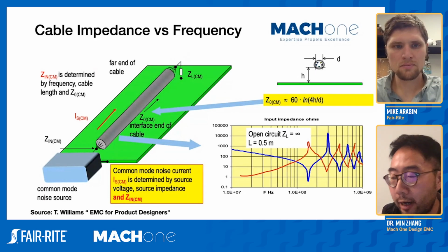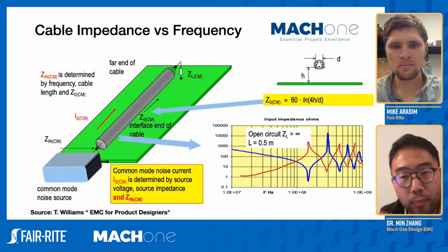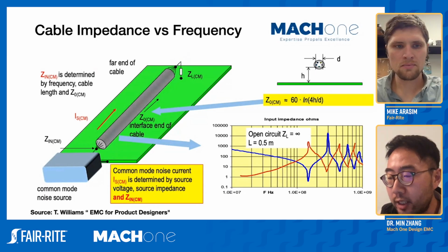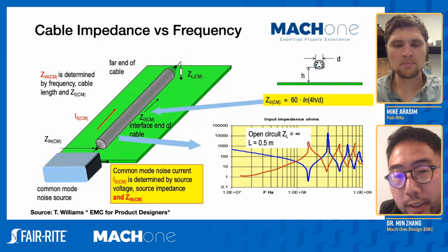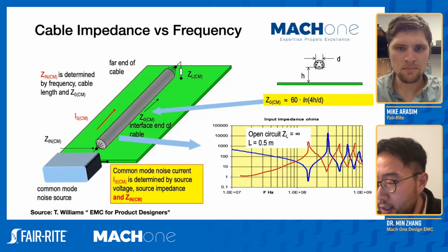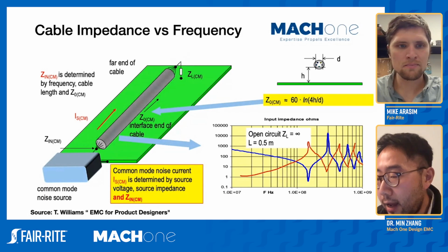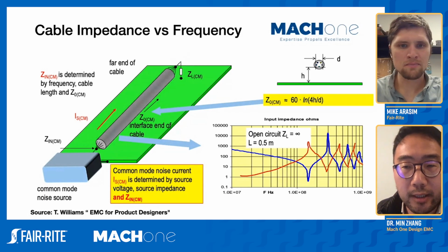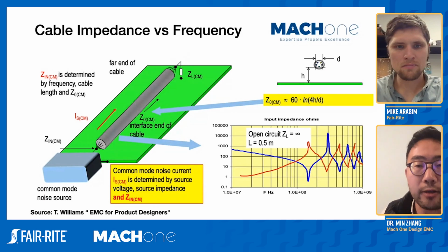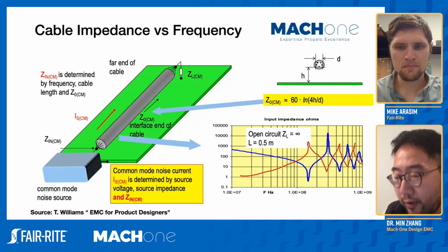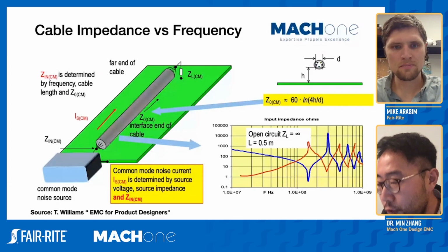So really, again, you just have all these uncertainties, and if you look at the equations we mentioned earlier on, you want the ferrite to be most effective when you put it at a lower impedance point. But because of this, the impedance always varies with frequency. So it's presenting a big challenge when we try to use ferrite. I guess this slide really shows you what we mean.